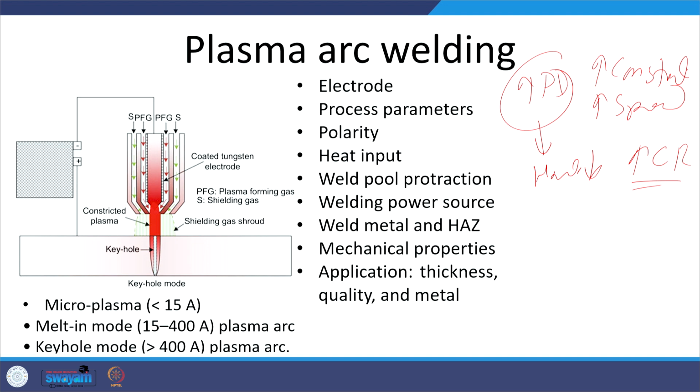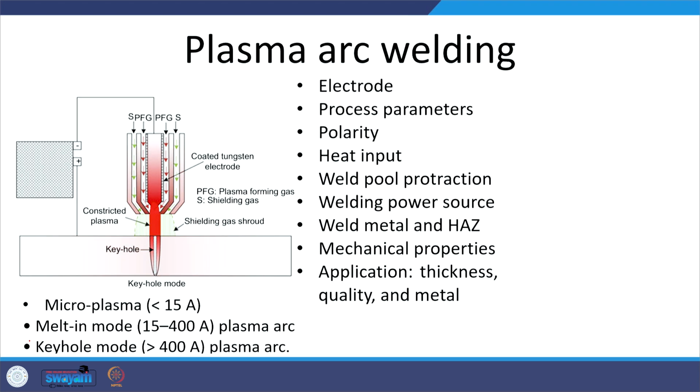Second aspect is, say these are the edges, and when a high velocity plasma is being used, it melts the thin zone. Okay. Because of the high power density at the center, the metal gets evaporated, and this in turn produces the hole. Okay. So, metal evaporation builds up the pressure in the molten metal. So, say this is the molten pool, and at the center is where power density is maximum.